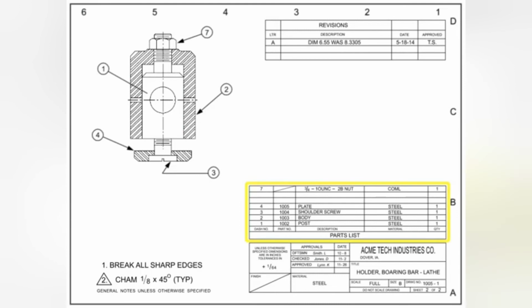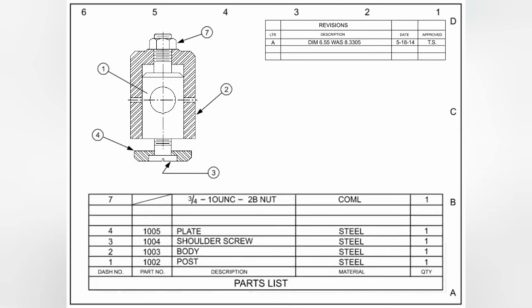The parts list, also called the bill of materials or list of materials, is a tabular list of raw materials or subassembly parts used to make an item. Used only on assembly drawings, parts lists are typically located directly above the title block, although some drawing standards put the parts list on its own sheet or even as a separate document. At a minimum, the parts list should indicate the quantity of parts per assembly, the part identifying number, and the nomenclature or description of the item. Most parts lists also include a material or finish description as well.